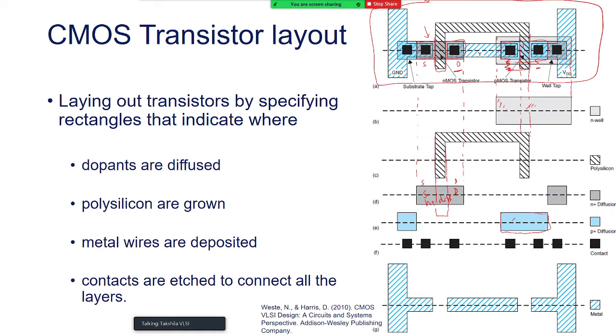Let's say this is source or this is drain and source. This is a symmetric device, so it doesn't matter. So this is drain and drain, they are shorted together, and that is the output terminal of the circuit. And then I know that two gates are connected, so this is the input of the circuit.